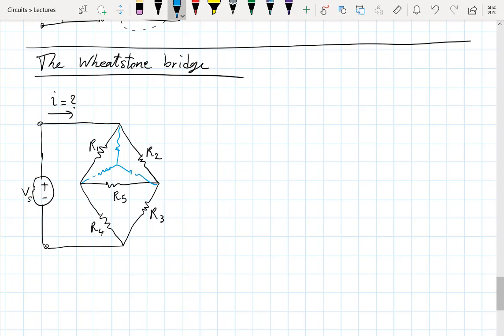Consider the blue resistors that I have used to replace the delta with. So now I have this blue resistor in series with R4, and then this other one in series with R3, the combinations of those in parallel, and that combination in series with this other up there. So I can get the equivalent resistance using wye-delta transform.